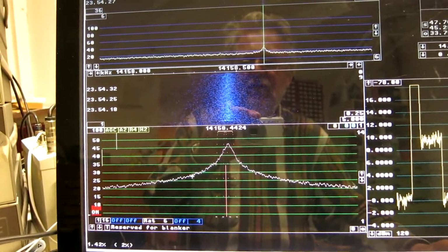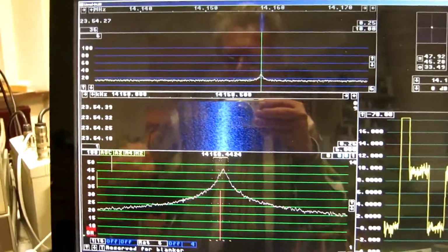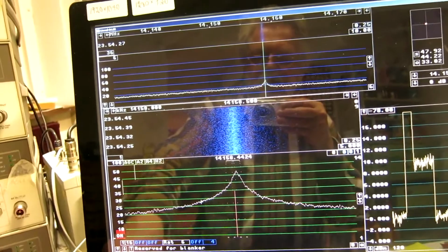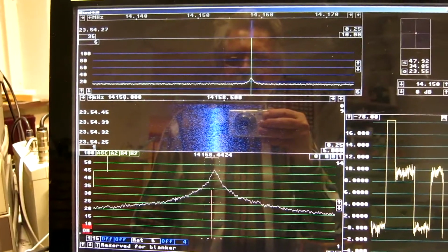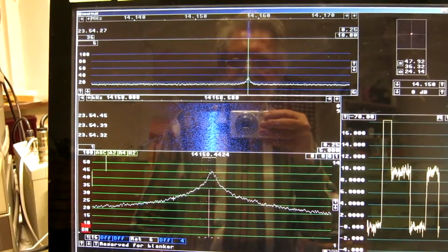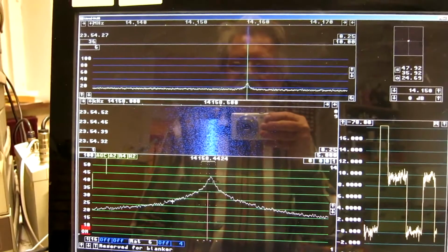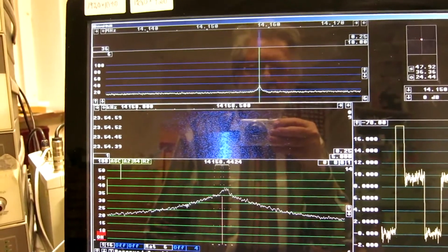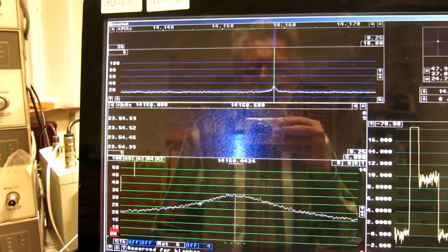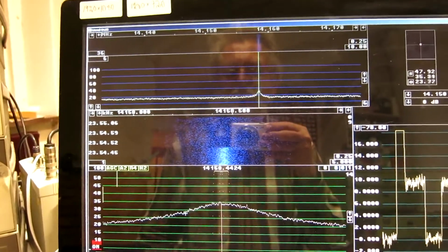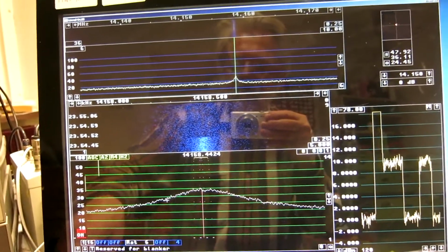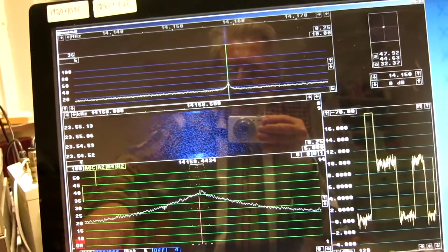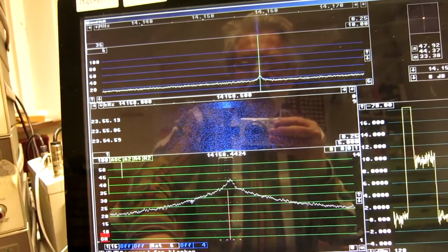Place the mouse there again and remove the positive feedback. And you can see the feedback seems to attenuate the noise rather than amplify it at a separation of 200 Hertz. So I add again and then set the attenuator to 4 decibels.